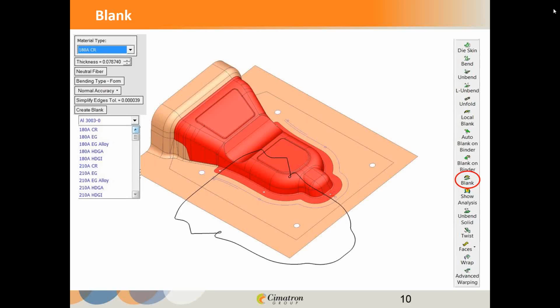It will make a huge difference, as you know. Stainless steel is not going to react the same as mild steel. And there are some steels out there now with a hardness that rivals the hardness of the die steel that's forming it. So it makes a huge, huge difference to be able to select the right material, not to rely on just mild steel all the time if it's a different type of part.